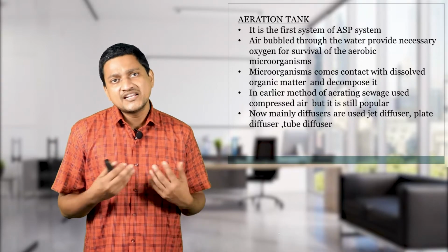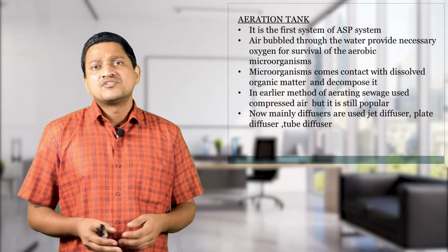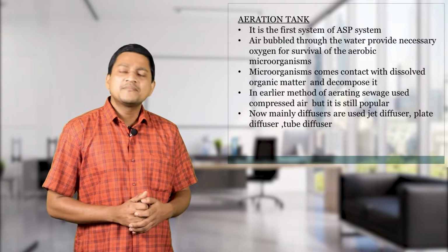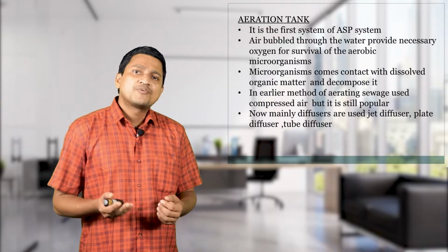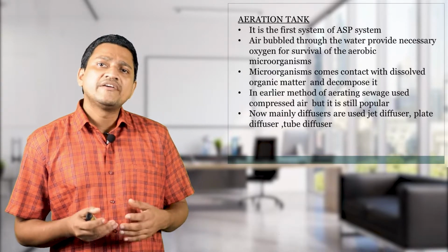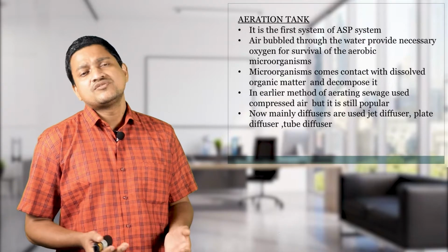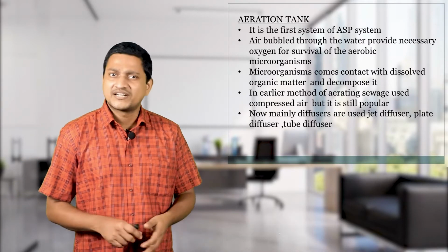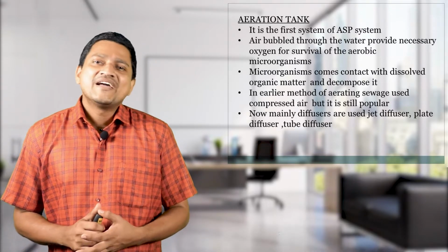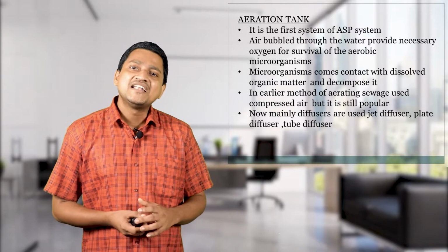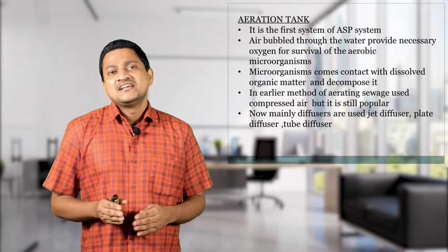First, we aerate the water by bubbling air through it, to provide the necessary oxygen for the survival of aerobic microorganisms. The purpose of providing aeration is to give the microbes sufficient oxygen to degrade the waste material present in the water. Microorganisms come into contact with the dissolved organic matter and decompose it.